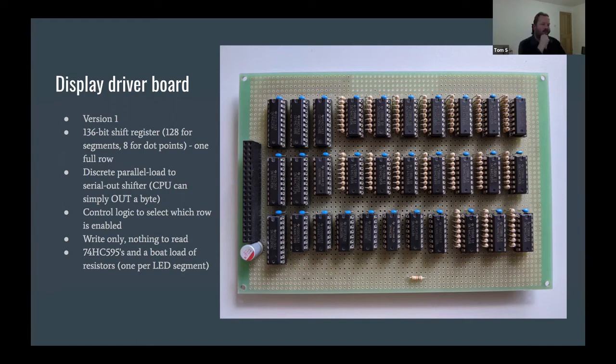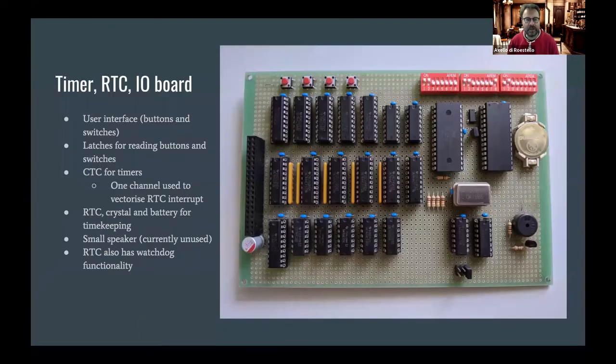Because you used them before. You used them on the other board, the single inline resistor network, the yellow thingies. Exactly. So you already have them, why not use them? But yes, about the anode part, if I had individual anodes and cathodes, I definitely could have used SIP style resistor networks to drive the displays.